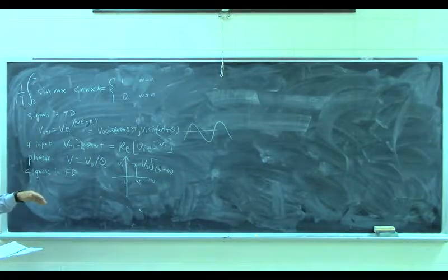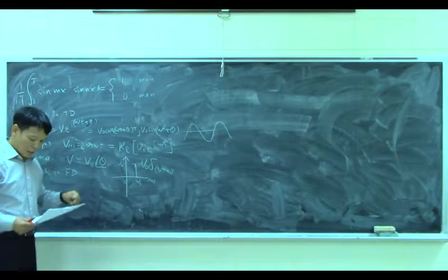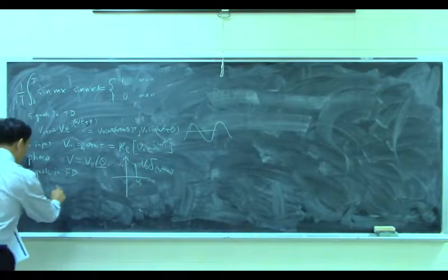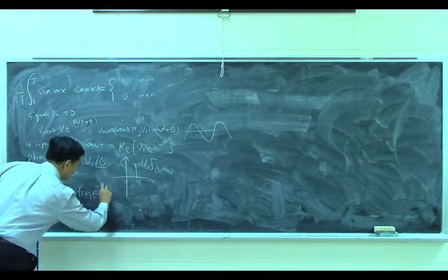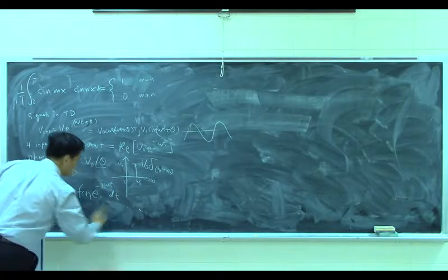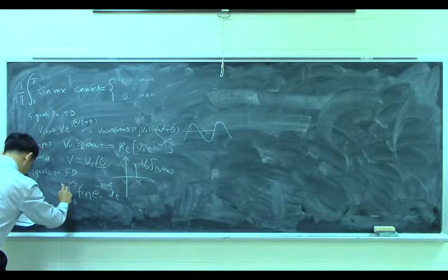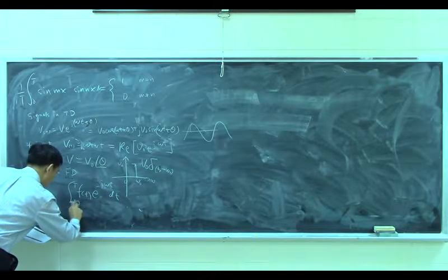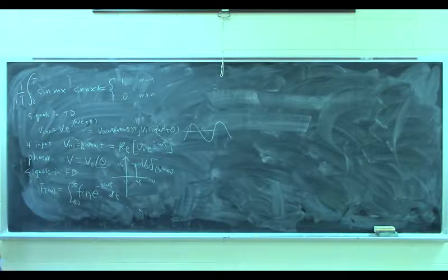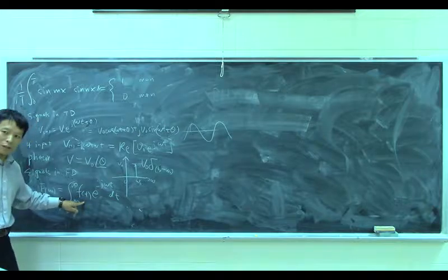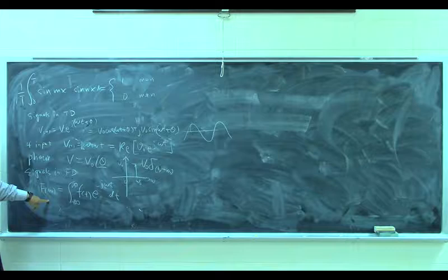From 323, we know they are related by the Fourier and inverse Fourier transform. If we are given the function f(t) in time, we multiply by e to the minus j omega t, then do the integration from negative infinity to positive infinity. This gives us the frequency component. So we convert a time domain signal through the Fourier transform into a frequency domain signal.